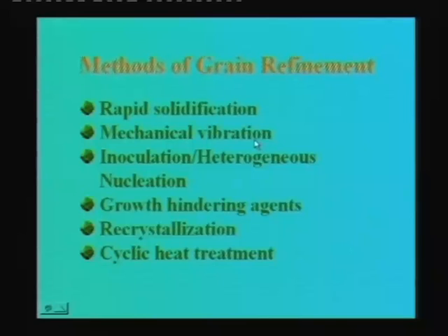There are different techniques nowadays available: Thixo casting, Rheo casting. These are all different casting techniques where you take the whole casting and then vibrate it, and when we vibrate it, what happens is the dendrites which have nucleated and started growing into the liquid, they break. So instead of a columnar grain, the columnar grains break into fine grains, and then they get distributed uniformly in the liquid, so that you get a fine grain structure.